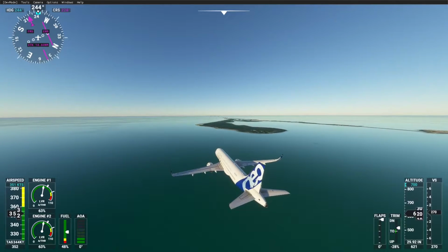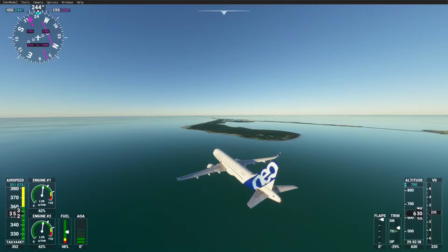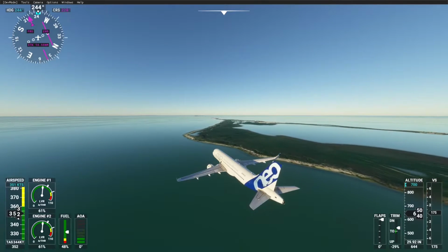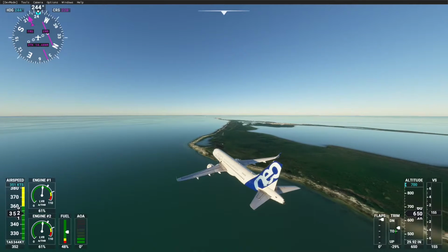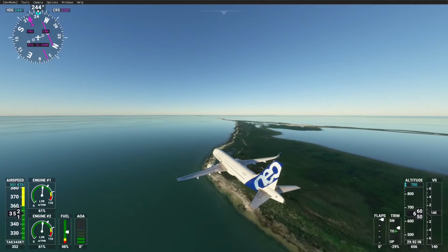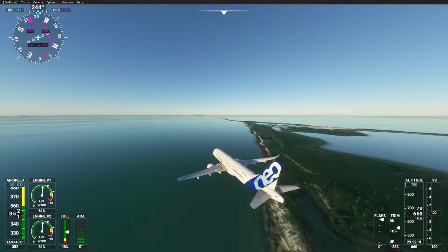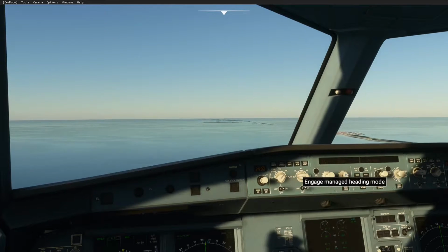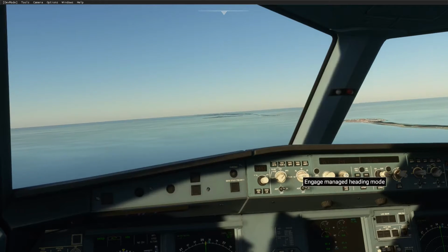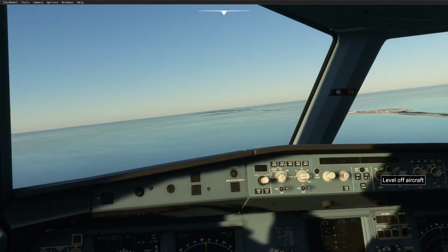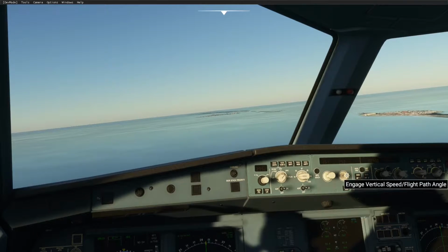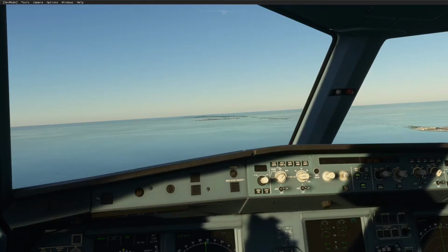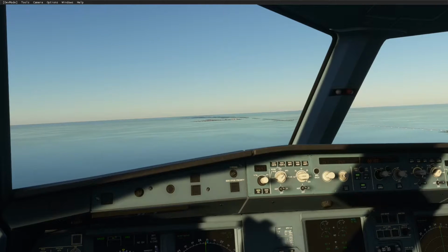We'll start with the air conditioning, and with that, this is the system that provides air at a nice temperature and a good pressure into the cockpit and the cabin. These zones are, there's three of them. There's the cockpit, the forward cabin and the aft cabin that we can control, and they're all controlled independently. The air normally comes from the pneumatic system, but it can also come from ram air or indeed an external low pressure air connection.